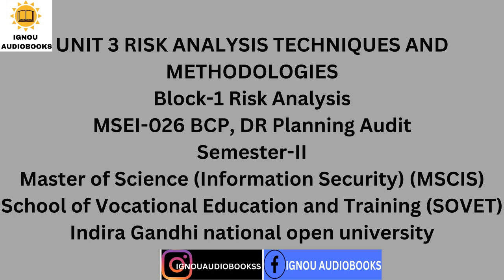3.5.1.2 Hazard and Operability Studies, HAZOP. The HAZOP technique was developed in the early 1970s by Imperial Chemical Industries Limited. HAZOP can be defined as the application of a formal systematic critical examination of the process and engineering intentions of new or existing facilities. It assesses the hazard potential that arises from deviation in design specifications and the consequential effects on the facilities as a whole.